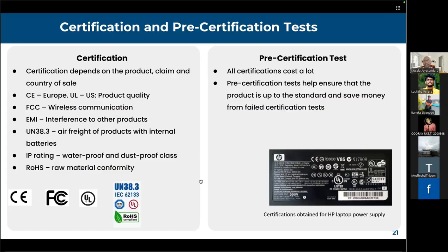Unfortunately, in Sri Lanka, we don't have much pre-certification facilities. In our office, we have a pre-certification facility. We can do almost all pre-certifications for electronics. We do that beforehand. Then when we are sure that we are okay with EMC, ESD and everything, only then we go to our certification parties to get the certification, because it's quite expensive to go to them, come back, go to them, come back likewise.